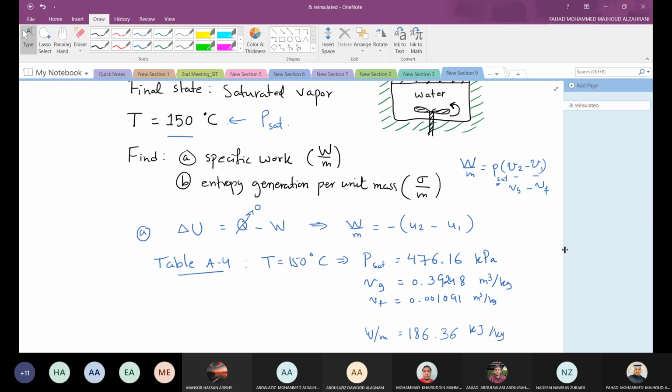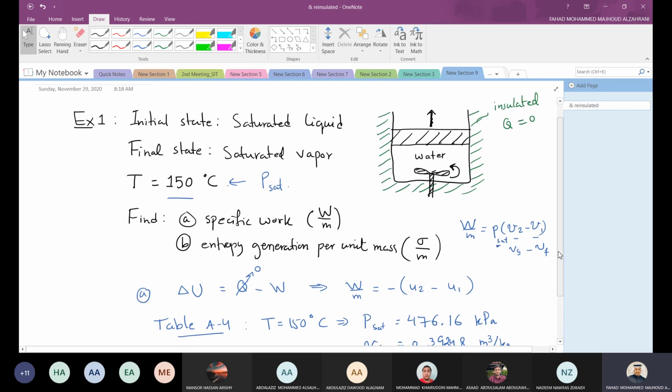Did you get the difference? When you have external sources affecting the system, applying work on the system, you cannot use it, because this is not solely expansion or compression work. It's not 100% compression or expansion. There is not only the system doing work on a piston; there is also something else doing work on the system. This value is like saying there is no fan, which is wrong. Did you get the idea?